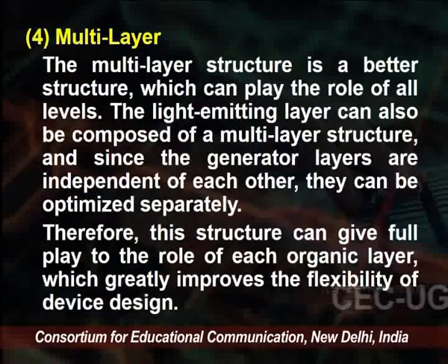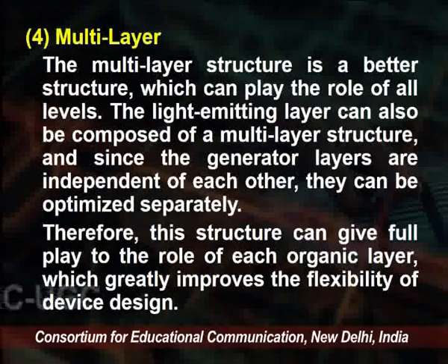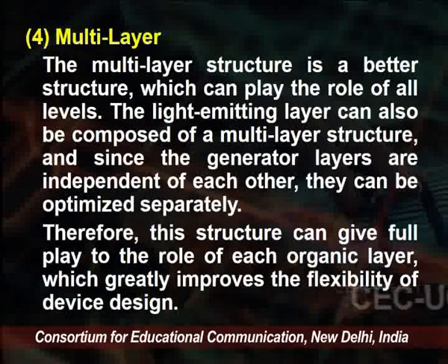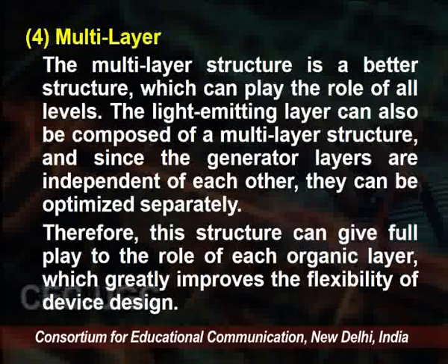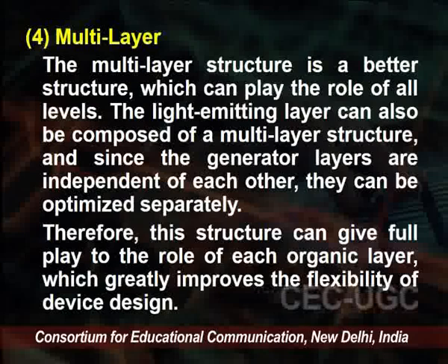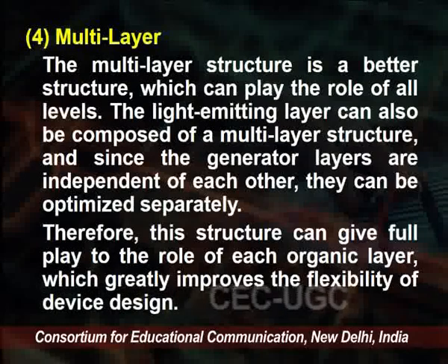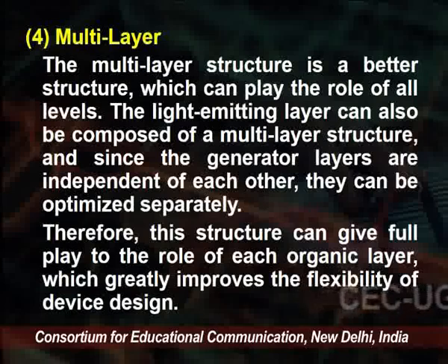Last but the important is the multi-layer structure, and it is a better structure which can play the role of all the levels. The light emitting layer can also be composed of the multi-layer structure, and the layers are independent of each other and then can be optimized separately, in which we can add or remove the layers. Therefore, this structure can give the full play of the role of each organic layer, which greatly improves the flexibility of the device design.